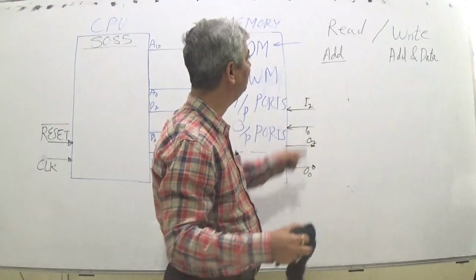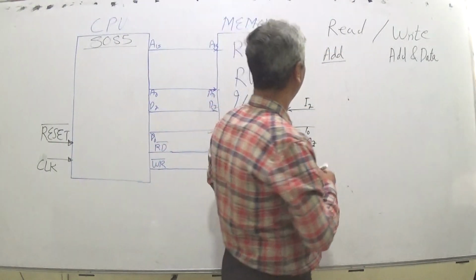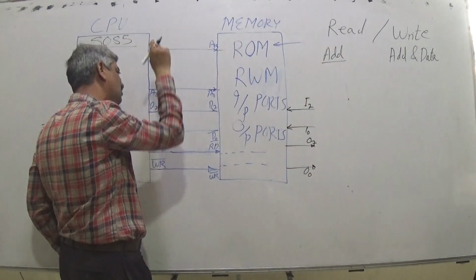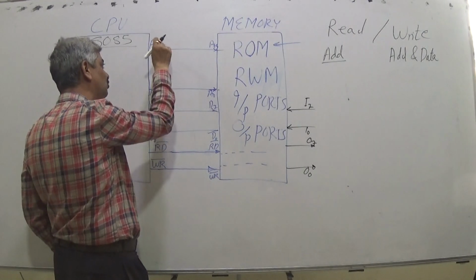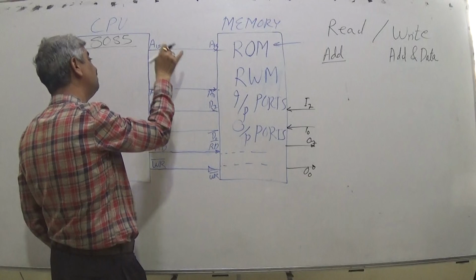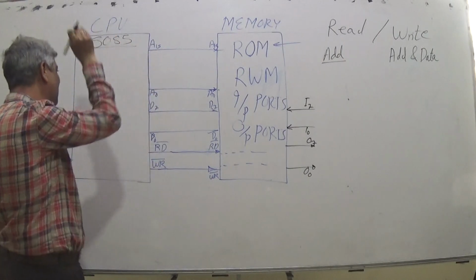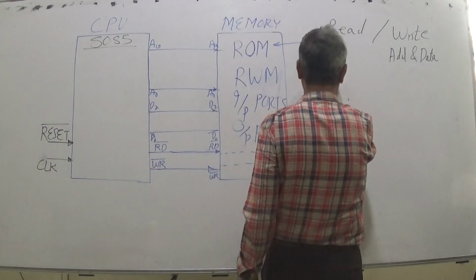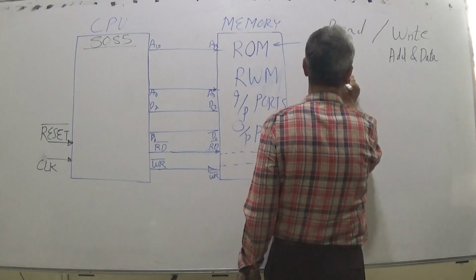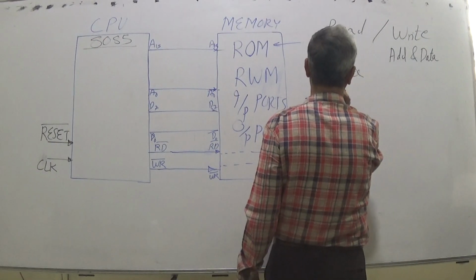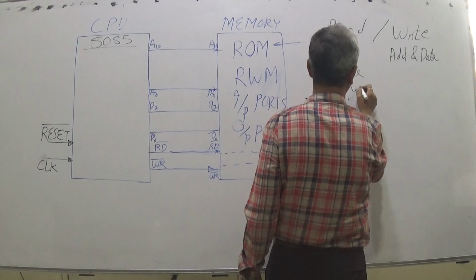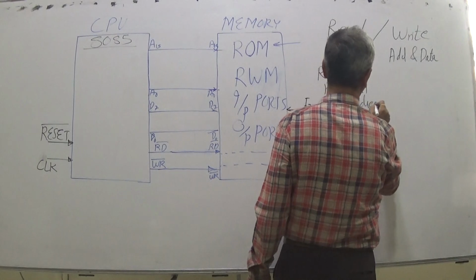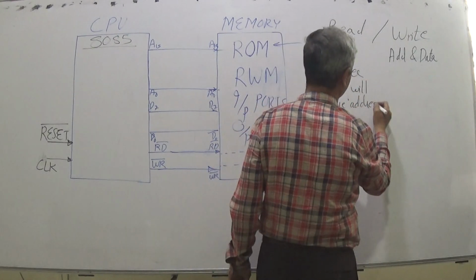So like that, in case of a read cycle, the address, a 16-bit combination, is appearing on the address lines. These pins of the microprocessor are becoming 1 or 0. So that must be given by something which is inside the microprocessor, which must be stored inside. So some register pair will give the address. Then it gives the address and the microprocessor activates read bar.